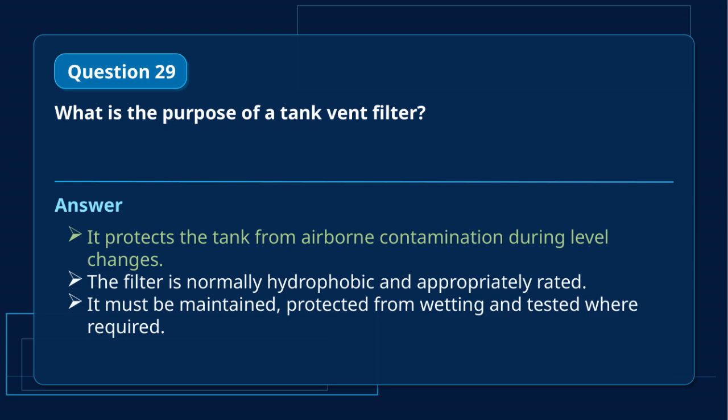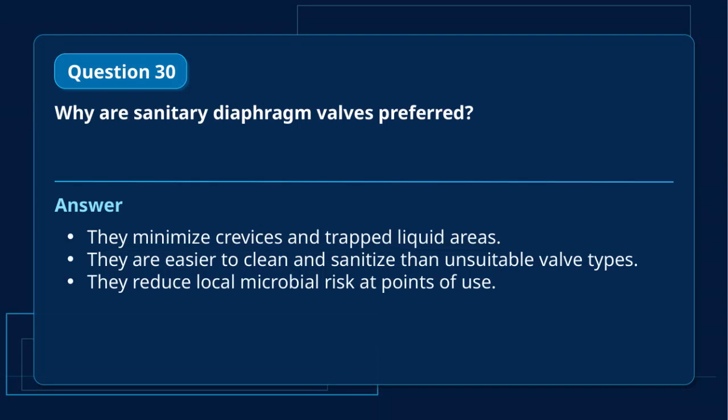Now, let's talk about why sanitary diaphragm valves are preferred in certain applications. These valves are designed to minimize crevices in areas where liquid can get trapped, which is crucial because trapped liquid can become a breeding ground for microbes.